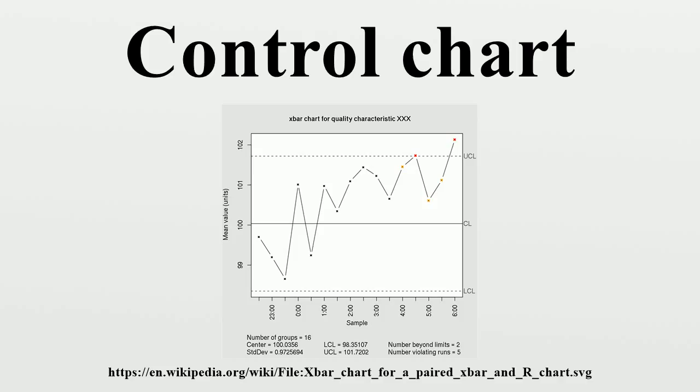Other types of control charts have been developed, such as the EWMA chart, the CUSUM chart and the real-time contrasts chart, which detect smaller changes more efficiently by making use of information from observations collected prior to the most recent data point. Most control charts work best for numeric data with Gaussian assumptions.